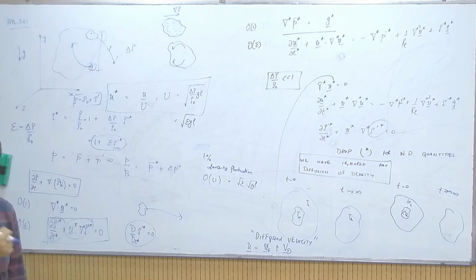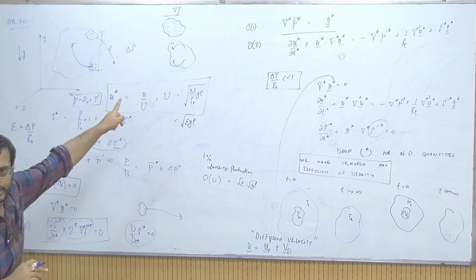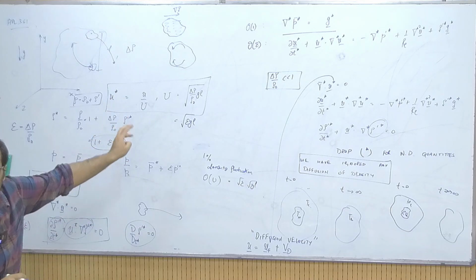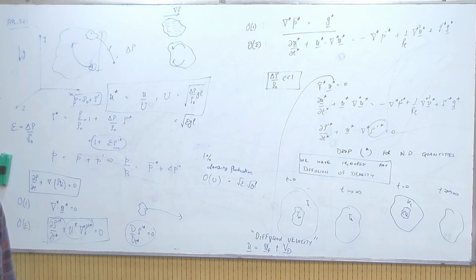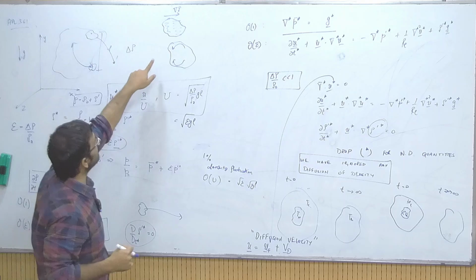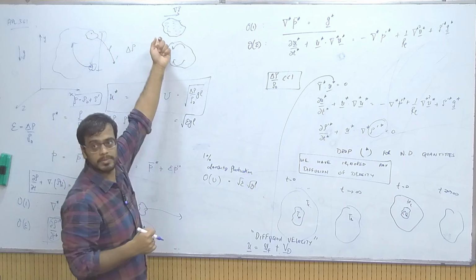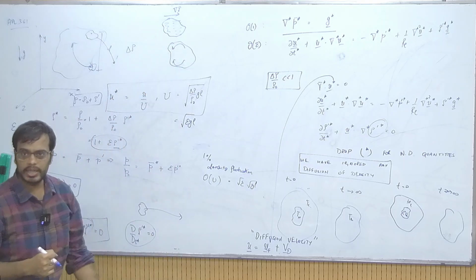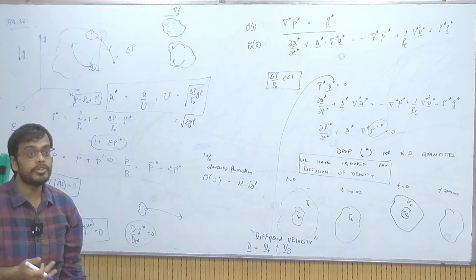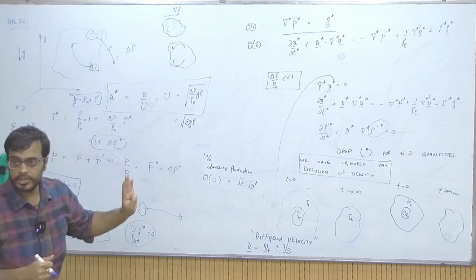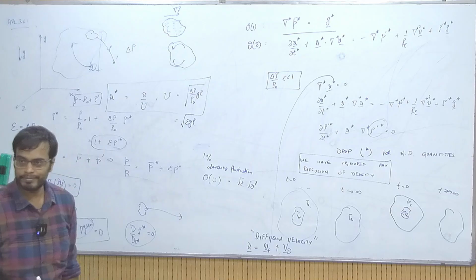It is the velocity of the center of mass. There is no flow happening, the fluid particle is at rest, yet the center of mass has shifted. This shift in center of mass has happened because there has been a gradient of density which diffused. If there was no diffusion, there won't be any shift in center of mass, there won't be any Vd.